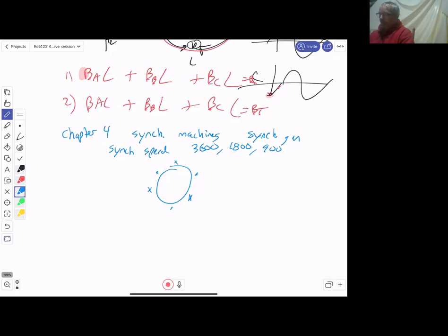What's different is the rotor circuit on a synchronous machine, and I'm going to show this as a salient pole, it's always going to have a plus and a minus winding. So it's either going to be a permanent magnet or it's going to be a DC source. And the reason being is because that always gives me plus minus here, and I always have a magnetic field that operates here. If I want a constant torque output of the machine, or I want a constant electrical output of the machine, the rotating magnetic field that rotates because of the AC waveform on the stator has to be distance-wise the same on the rotor circuit as on the stator circuit.